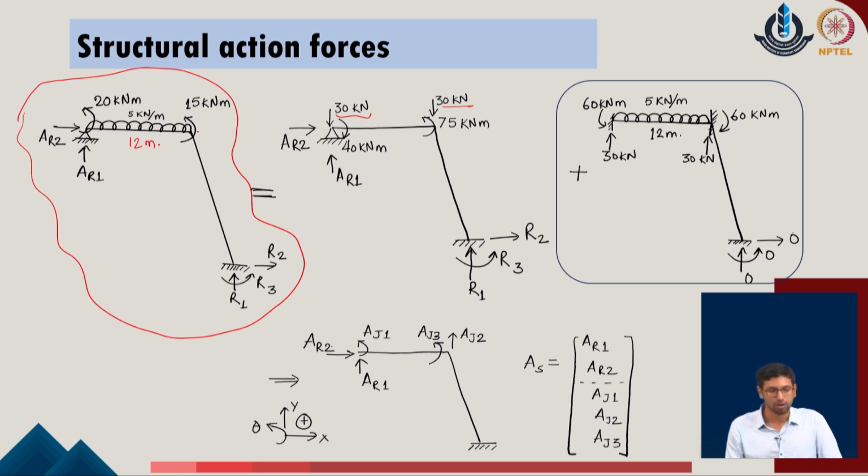We restrained all the degrees of freedom and converted the equivalent loads into the fixed end reactions of the given problem. The amount of the fixed end reactions which we have obtained, we just reverse their directions and provide them on the originally existing system, and that becomes the equivalent joint load of the given problem. So, this is how we have defined this 30 kilonewton over here as the equivalent joint load in the vertical direction.